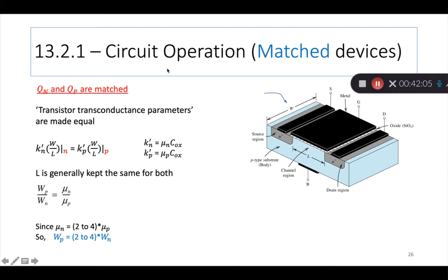During the effort to understand what happens when input is low, when input is high, and as the input goes from low to high or high to low, there is a certain process, right? The currents don't just wait for the inputs to go totally from one to the other, they also start to do their things. The devices are in a dynamic period for a very short time. To understand all that, you first need to understand this concept of matched devices. So what is a matched CMOS pair?